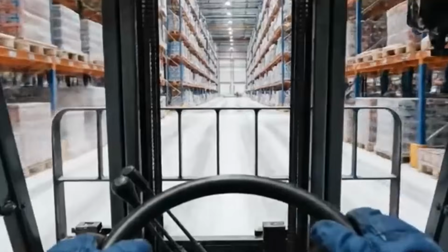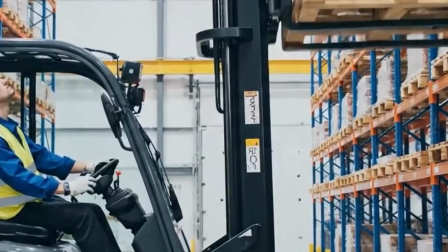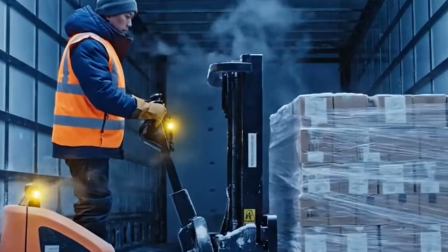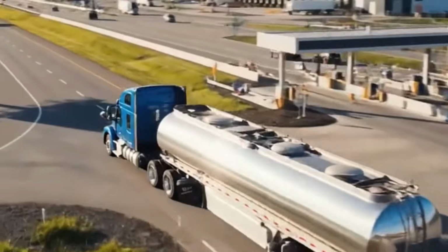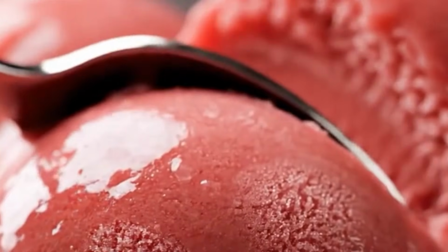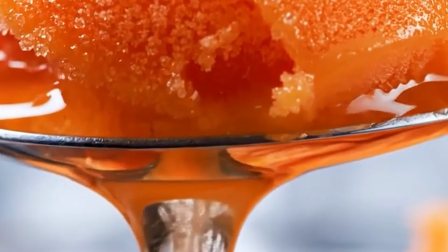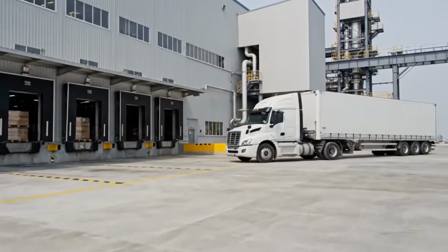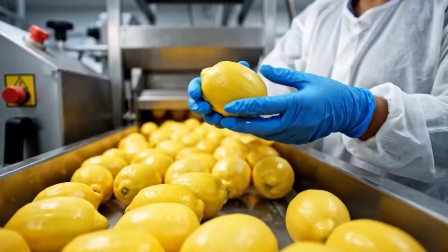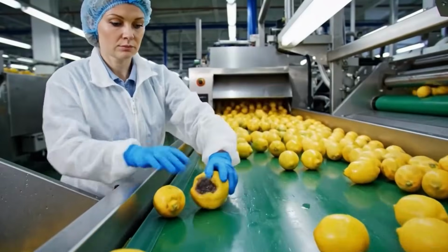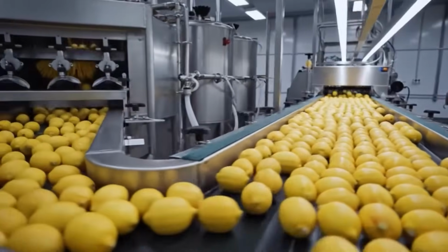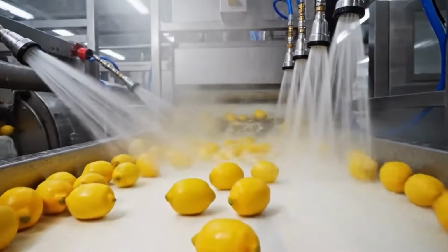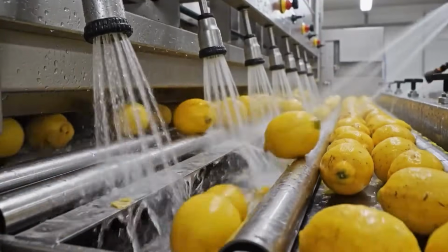After aging, the mix is transferred to continuous freezers for dynamic freezing. These are horizontal barrel-type scraped surface heat exchangers with internal rotors spinning at high speed. The internal barrel is cooled by ammonia or freon-based refrigerant, keeping the wall temperature at -25 degrees Celsius to -30 degrees Celsius. The mix is pumped into the barrel at 4 degrees Celsius and partially frozen in under 30 seconds. Rotor blades scrape frozen mix from the walls, maintaining even temperature distribution and preventing ice crystal buildup.